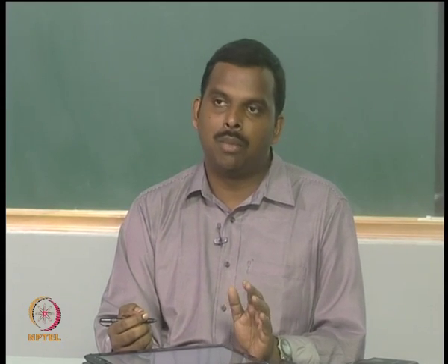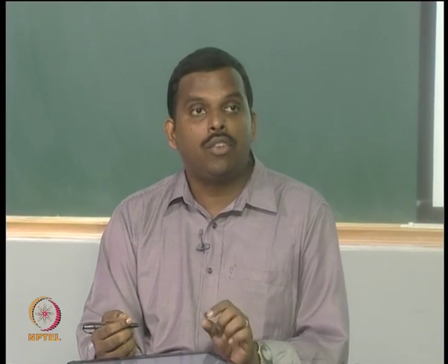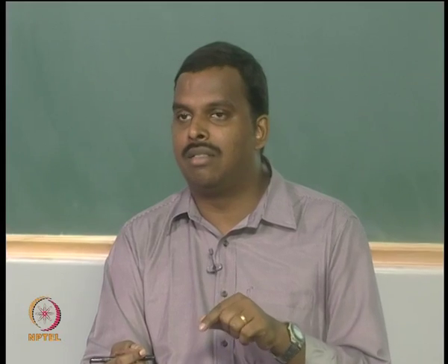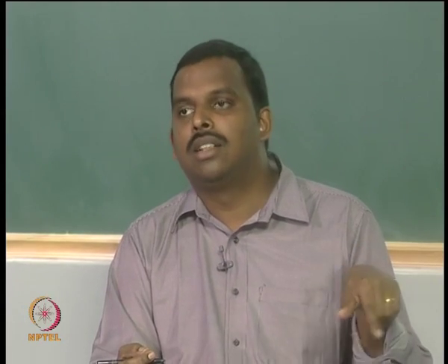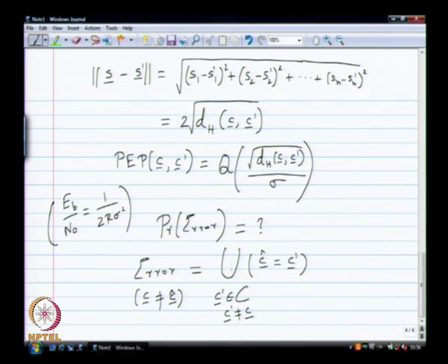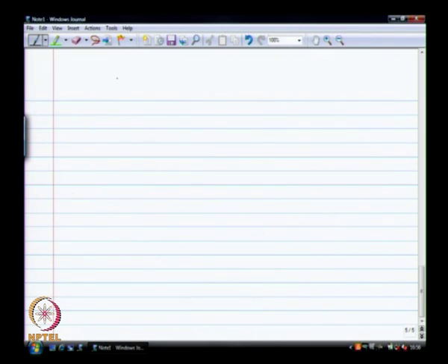So what do I mean by closest code words? The code has a certain minimum distance, let us say d. You only have to look at those events which are very likely to have happened, which means you only look at those code words which are at distance d from my transmitted code word, and take a union only over that, and then do a union bound with that. It is clearly not the complete error event, only something like a closest code word error event. So you define some other error event, which I will simply call error again, but remember this is not the same error as before. This one is: distance between C hat and C is equal to d, where d is the minimum distance of the code.